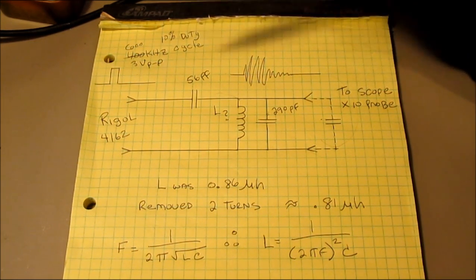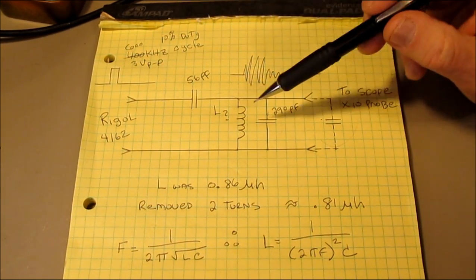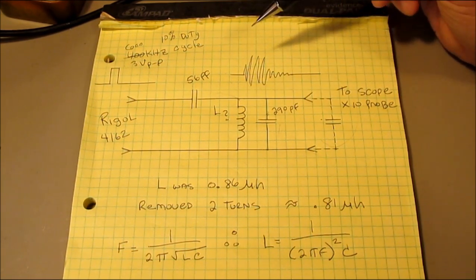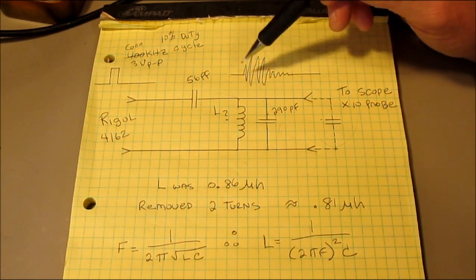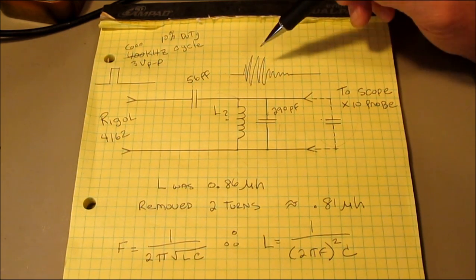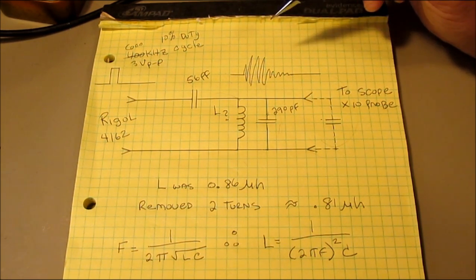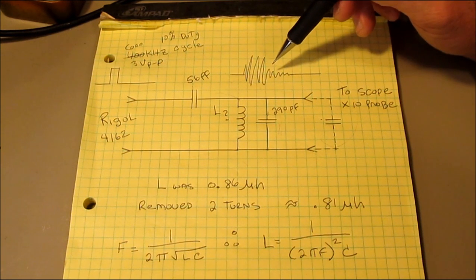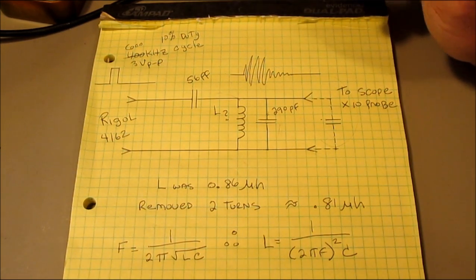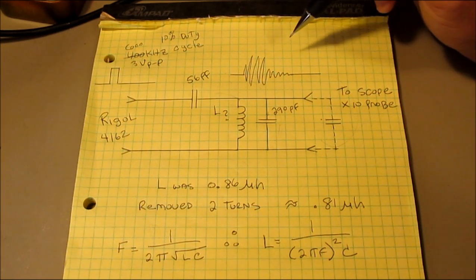And so basically, when you hit a resonant circuit like this with a pulse with some energy, it will naturally ring or oscillate at its resonant frequency. And so you can take that waveform on your oscilloscope and measure the frequency of it, either by measuring the time for one cycle and doing the math for that, or with the newer scopes, you're able to have it measure it by using the cursors on the scope. There's cursors where you can do that, and it'll give you all the data associated with those cursor positions.